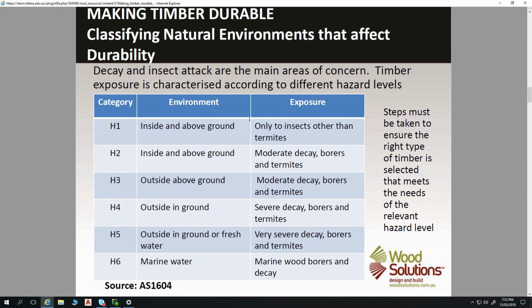different types of timbers have their different durability gradings, and you can buy a specific type of timber which has a specific type of treatment, which will have its durability grade at either H1, H2, H3, H4, H5, or H6. So a typical piece of timber that you will specify in a house frame are your fascias.